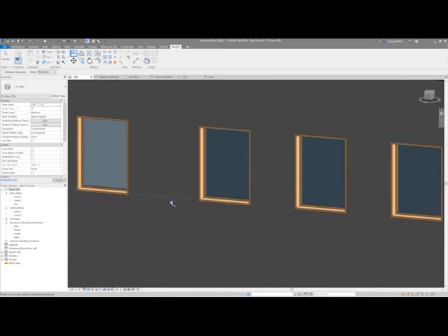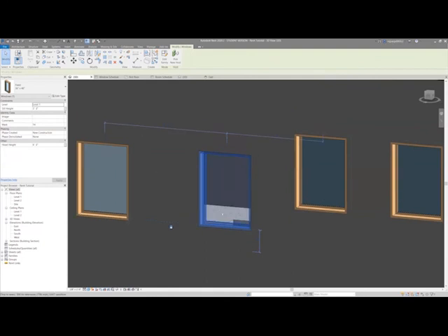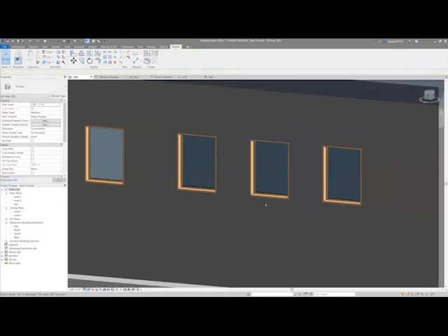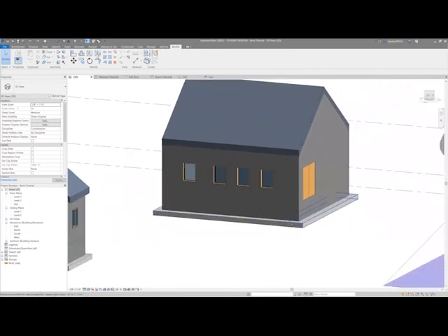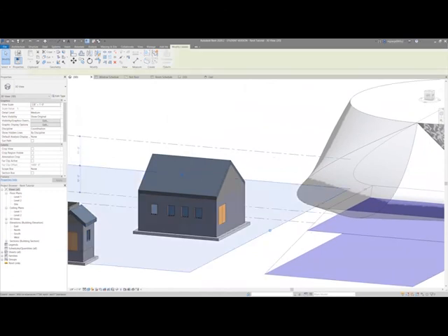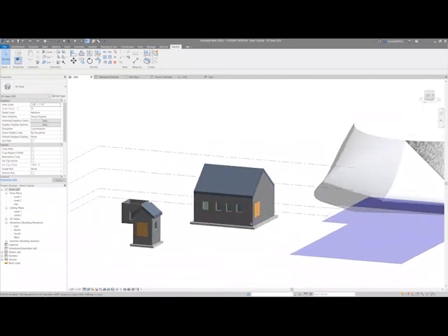What you're seeing right here as well is the lock, right? And this is kind of the basis of making things parametric. So when you align something and the lock goes there, you can just click that, and that immediately associates it with this right here. So if I move this, this goes with it. And the same thing with all these, right? If I aligned and locked all these, then yeah, it would move. And where it gets wild is that's with everything. If I lock in the levels at a certain distance and move them up and down, then that gets into it.